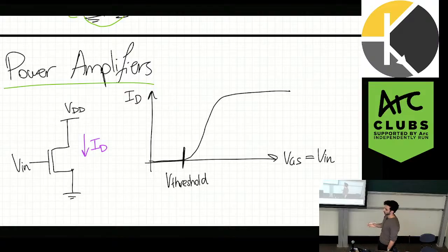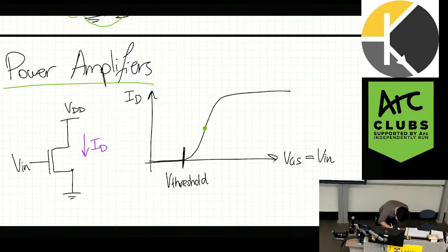Now, the best way to think about the power amplifier is to imagine it like a valve, right? So from this region, you can imagine you're trying to turn the valve, but there's a lot of friction. So you have to turn it a lot before you actually see something come out of the spout, right? Like, let's imagine it's water. You turn it a little, there's still no water, then all of a sudden at some point water starts flowing, right? And the more I increase, the more I twist that valve, the more water that flows, okay? So class A operation sits in the middle here.